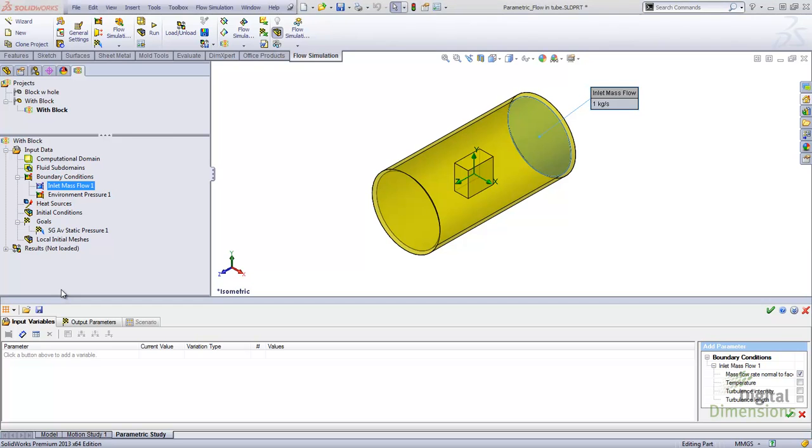We've also broken down our interface into two types, the what-if type and the goal optimization. The what-if mode allows you to go in and vary a set of selected parameters, such as dimensions, any input boundary conditions, and it allows you to explore your results. Goal optimization allows you to vary only one of the selected variable parameters in order to obtain a specific goal in mind, essentially allowing you to either vary a specific dimension or other input to get the desired goal.